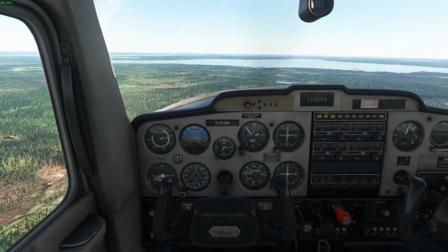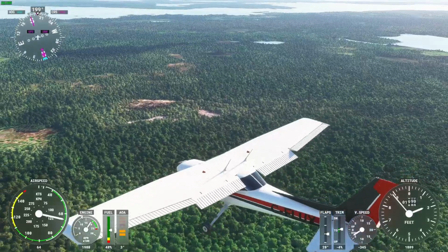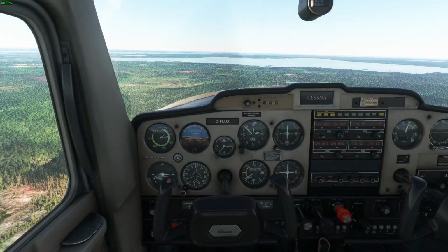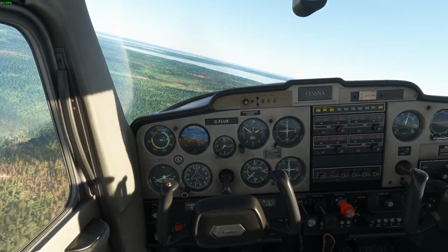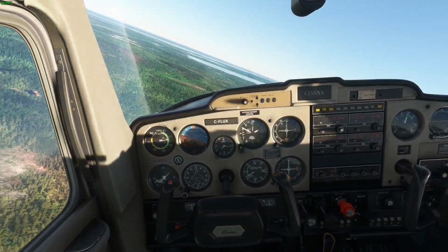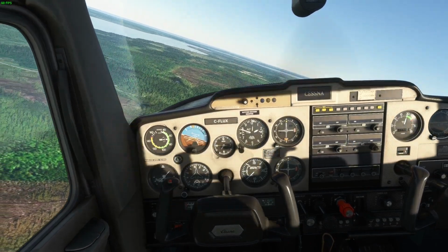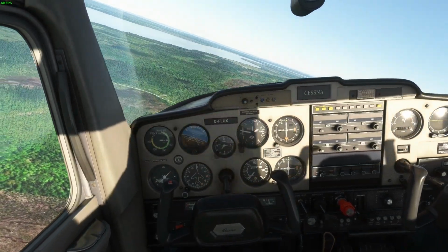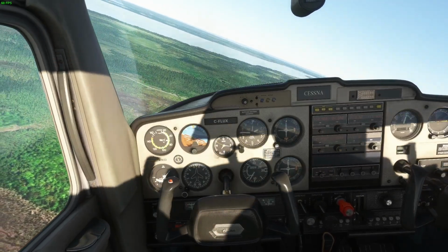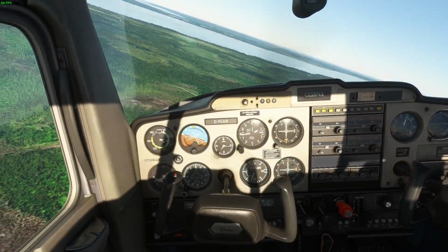So we're about 60-65 knots. There's the flaps down to 20 degrees. Repitch the plane, or retrim the plane. Initiate our turn, descending at 500 feet per minute. Power is down to about 1900 right now. It'll go a little lower until the turn's over, then we'll drop it a bit.